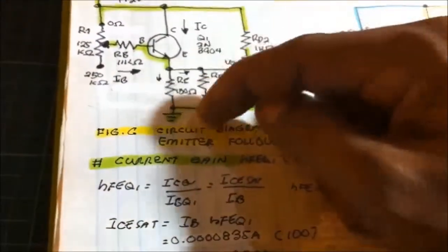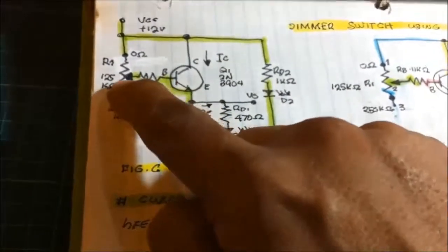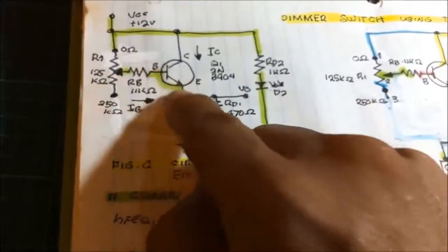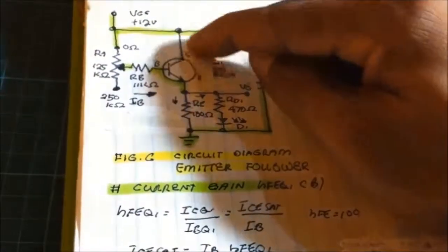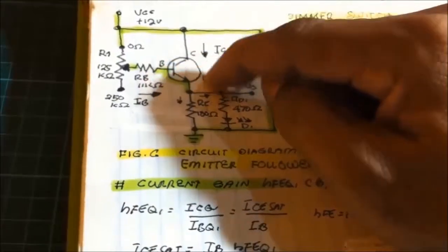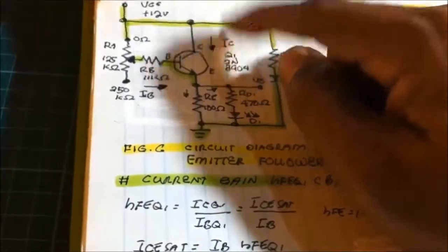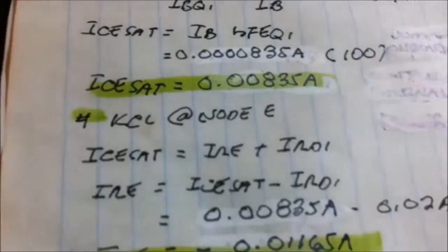That's why this LED turns off once you increase the value of the base resistor, making this not totally cut off, with the collector current very small because of the resistance of the base.